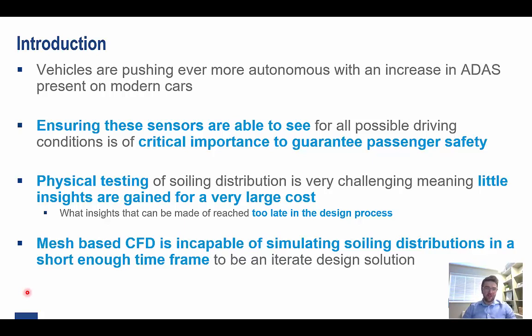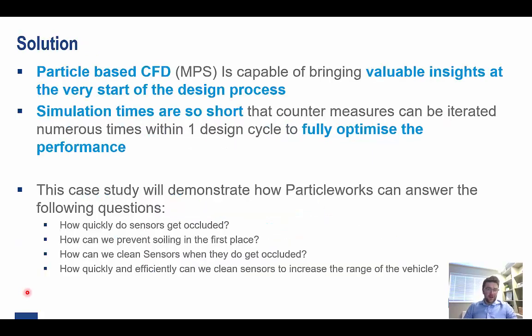So in order to have an accurate simulation, we may be able to get one simulation done if we start it right at the beginning of the design process, which again is nothing more than a verification test, whether or not the design is going to work. But then it's too late to do any iterations, and we wouldn't even be able to do any iterations in the virtual world anyway using mesh-based CFD. So all that leaves us is a particle-based CFD tool, such as Particle Works using the MPS method.